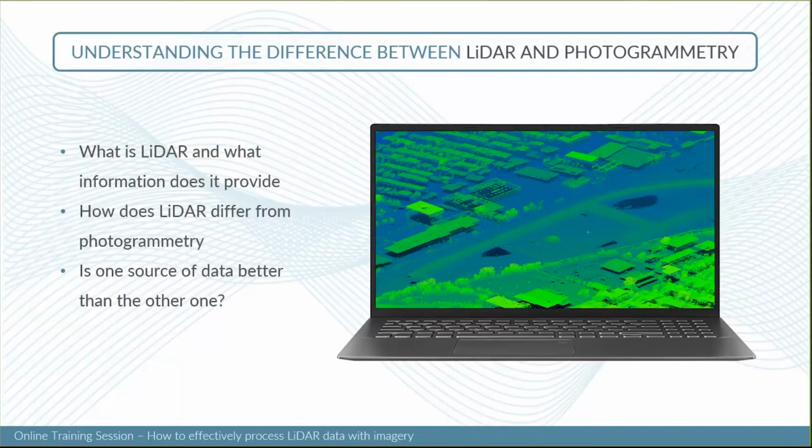Since if you want to classify your point cloud as ground or non-ground, or also vegetation or non-vegetation, depending on how far you want to go with your analysis. As for photogrammetry, the advantages, I think the first one is it brings out the color to the point cloud, which is a big plus compared to LiDAR that doesn't really have this color. The color is much more human friendly because it's easier to analyze since you have the RGB information.